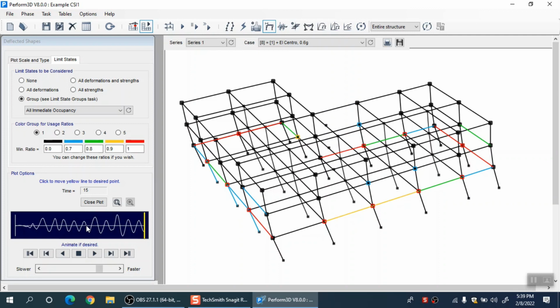Actually, this data is plotted, it is actually plotting the state of each element, the damage of each element for each time instant, right. So, you can get this data extracted from the program after the analysis and exactly see for how much time a particular DC ratio increased from 1, and then base your decision making on that. So, there are ideas like if for a very small instant the DC ratio goes beyond 1 and then comes back,